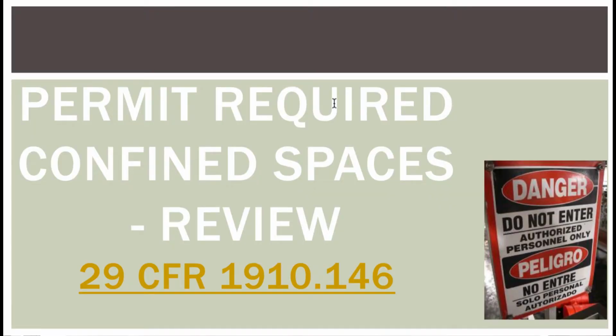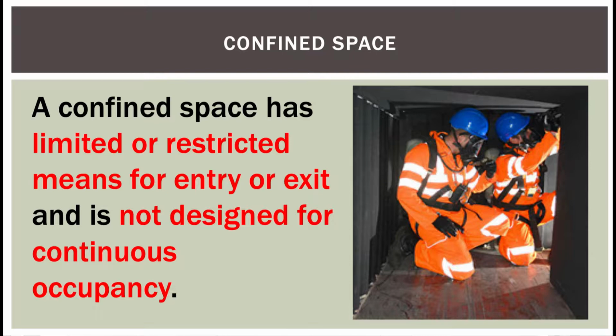Okay, so we moved from flammable liquids to a quick review of confined spaces, which is found under 29 CFR 1910.146. And that is just because of this principle of the lower explosive limit and having to do atmospheric monitoring inside of confined spaces. And we want to bring all this material together to make a useful package of information for us. So a confined space has a limited or restricted means for entry or exit. It is not designed for continuous occupancy.